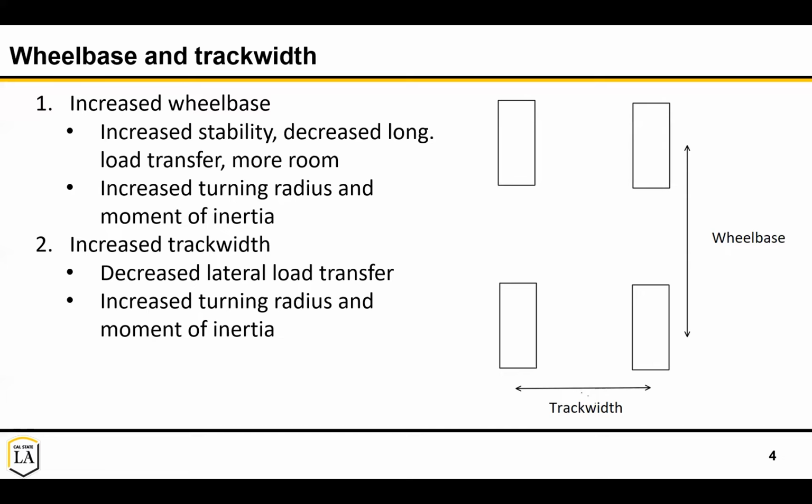But just to give you some rough rules of thumb to get you going, for example, go-karts, where you have these very slow, very windy tracks, will usually have roughly track width equal to the wheelbase. And as you go to higher speed race cars, your track width might get to about 60% of the wheelbase, and then you might have cars that don't do a lot of turning and are just straight line, like dragsters, and your track width might be about 20%.